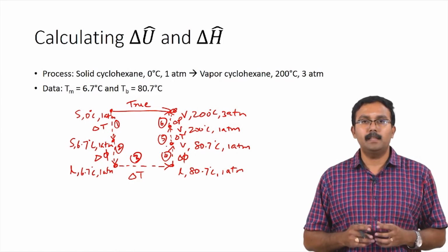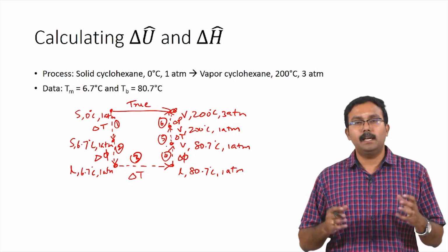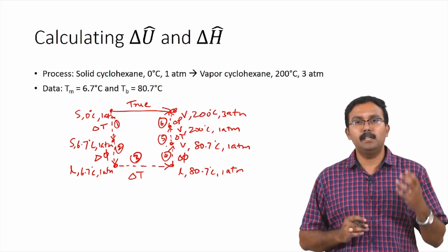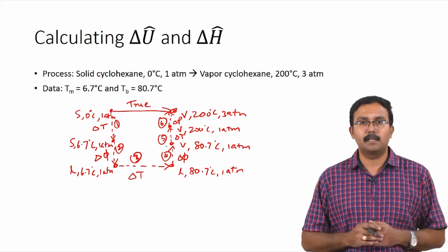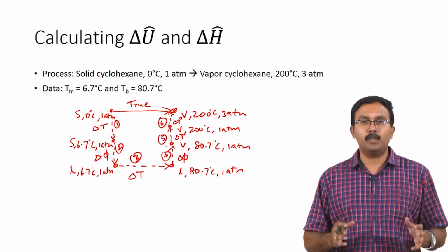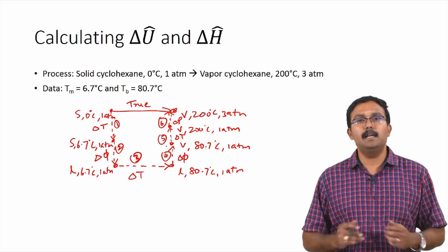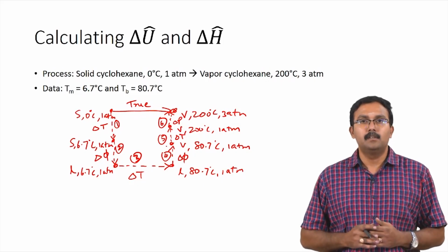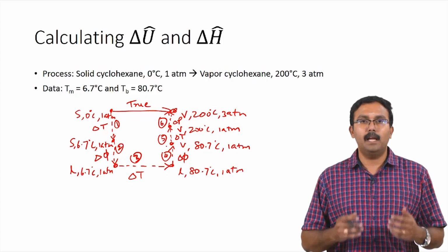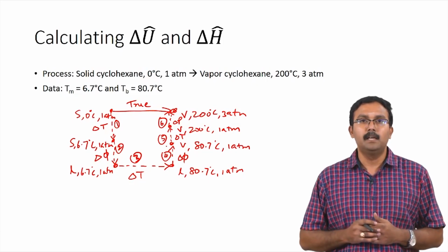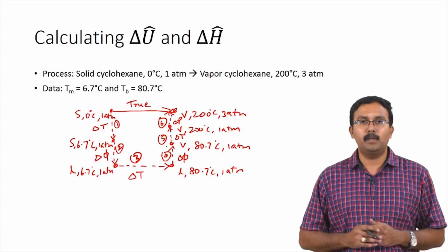So the summation of the enthalpies for each of these steps can be brought together to give you the total change in enthalpy for the overall process which has been described. This process which we followed is called building a hypothetical path. I will give more tutorial problems and exercise problems which will help you build this hypothetical path. This is not the only hypothetical path you can build.